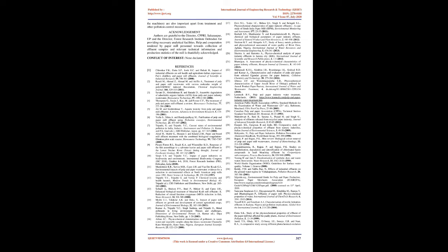The values of TSS in effluents from all the four streams were found to be higher than the WHO maximum limit of 100 ppm, 100 mg/L, for discharge of wastewater to surface water bodies. Suspended solids reduce the rate of photosynthesis by aquatic flora and benthic organisms, and retard the efficiency of biological treatment processes. 35. 6. Determination of turbidity.